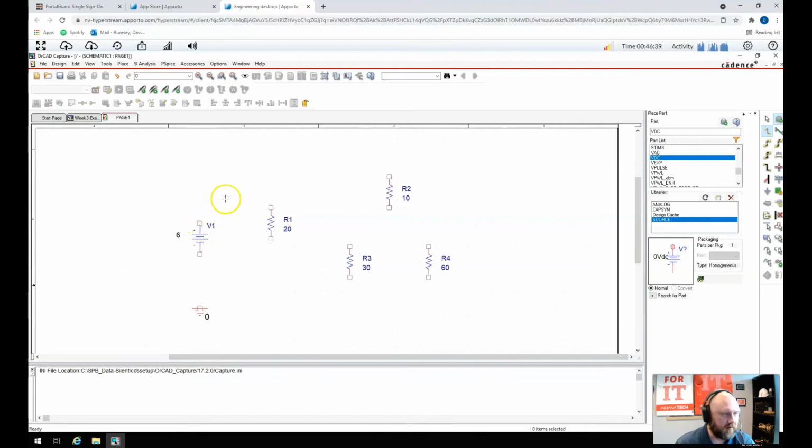Now, I want to connect all these things, and there's these nice little square points here. So I'm just going to go inside one of these squares. You don't have to be exactly in the center of it. I'll just kind of be off the side there. And you can see it kind of puts me in the center of that square. And I can see a little wire getting built up here. Now you see if I go straight down there, it makes a connection. But suppose I want the wire to go all the way up to here, just because I want to do it for visual sake, for making it easier for me to look at the diagram. Well, I can do that and then left click.